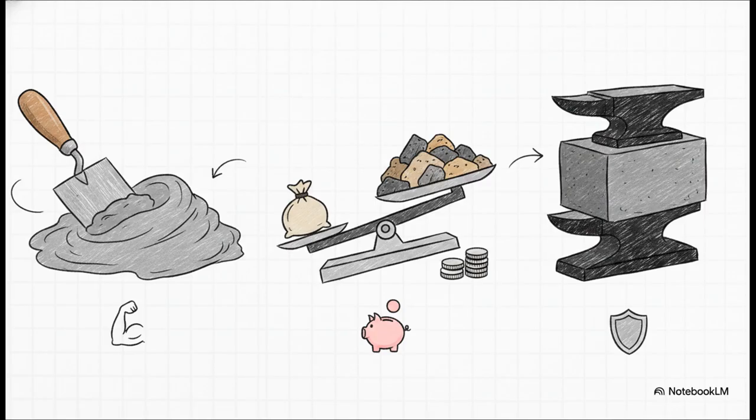Number 2, economy in cement use. Listen, cement is the expensive part. By perfectly filling the voids with cheaper rocks and sand, we save a ton of expensive cement, which is economically vital. And number 3, higher density. Less trapped air means denser and significantly stronger concrete.